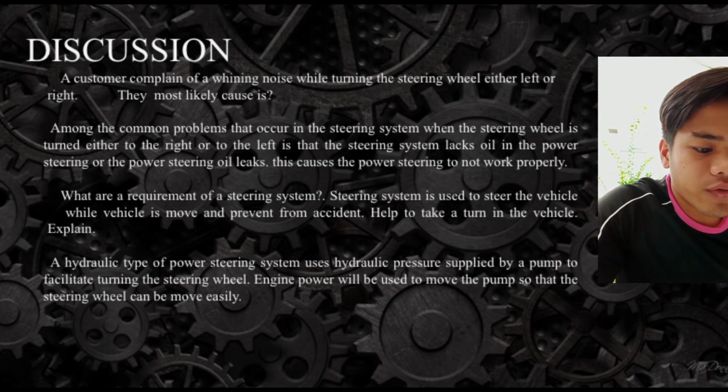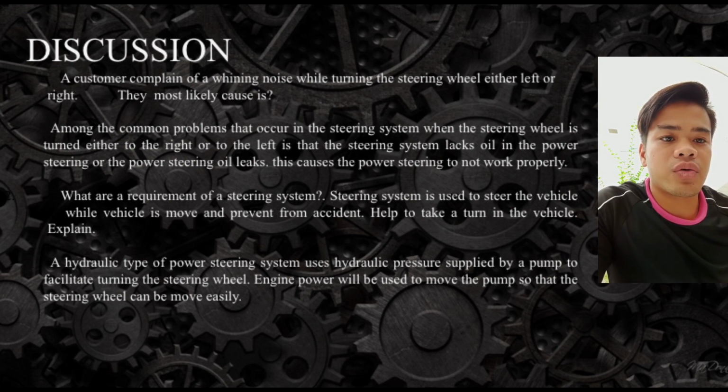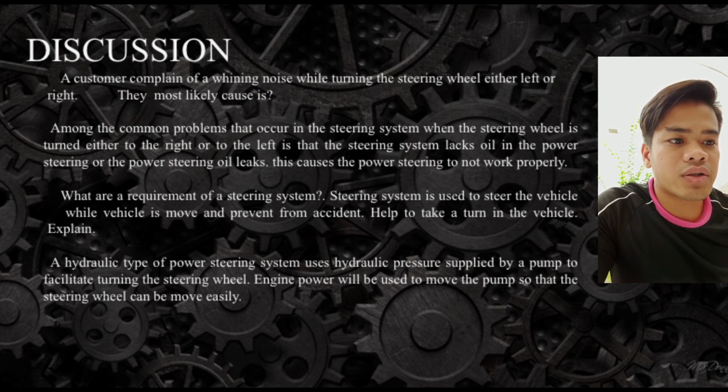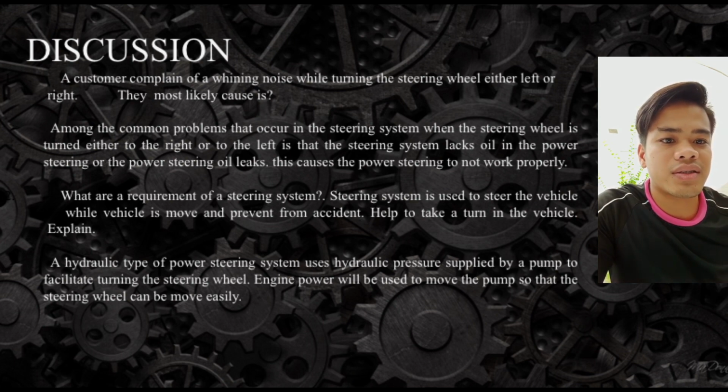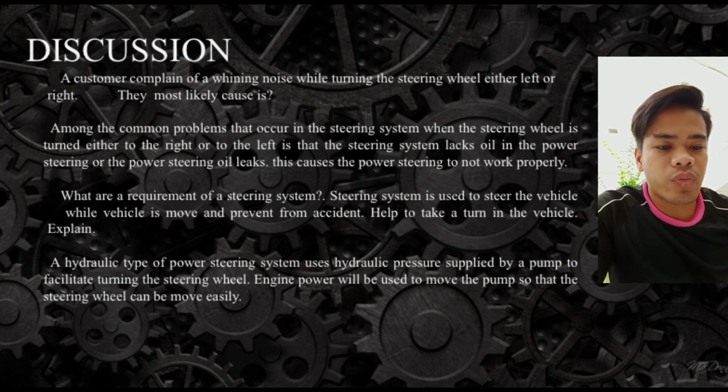Discussion for the vehicle steering system. Question number 1. A customer complained of a whirring noise while turning the steering wheel either left or right. The answer is, among the common problems that occur in the steering system when the steering wheel is turned either to the right or to the left is that the steering system lacks oil in the power steering or the power steering oil leaks. This causes the power steering to not work properly.